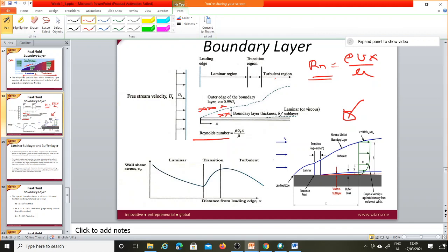If you are not focusing on this boundary layer, why are we studying it? If you don't study the boundary layer, you will not know the losses, and you will design ships or nozzles without considering this loss, so the delivered output will of course be less than you expect. So you always need to consider this loss and add it to the design.